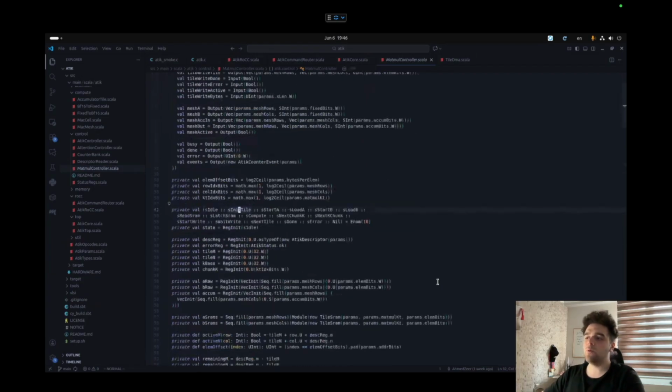Then after that, we are starting the A operations. What that means is we are going to load from the main memory to the SRAM that we have. That is load A. Then we're going to do the same thing for B. Then we're going to read from the SRAM to the registers, and we're going to latch this data, and then we're going to compute.